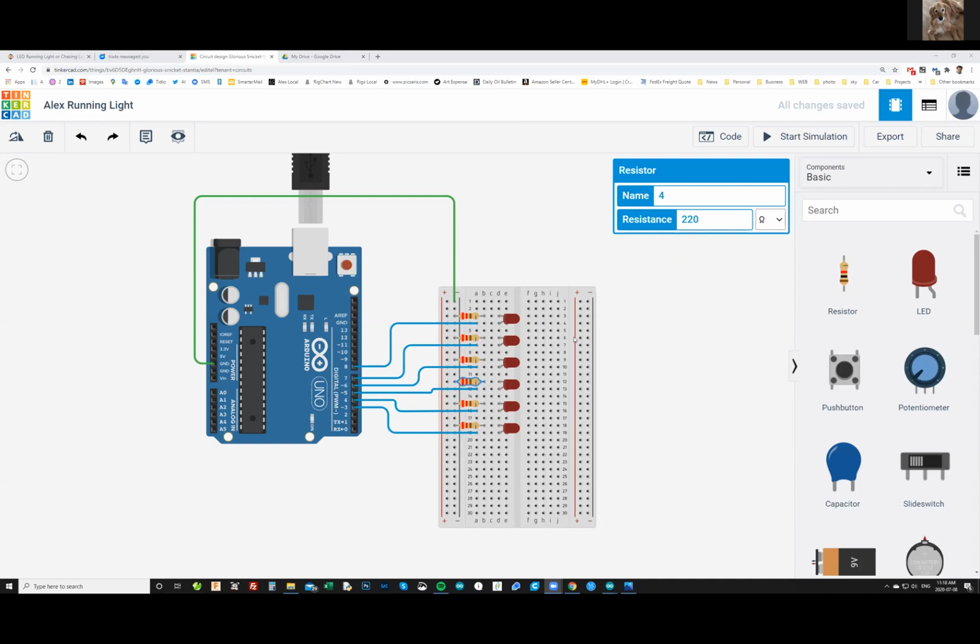Oh my god, these resistors are so annoying. Guys, try to bend it closer to the body of the resistor, like I do, for example, like so, so that you can get it in. Right, and then just plug them in vertically. I don't find any difficulty plugging them in. Whenever I try to put the resistor in, it just bends the wire. Don't force it too much. Try to do it gently. If you do it a little wiggly, it'll usually go in easier.